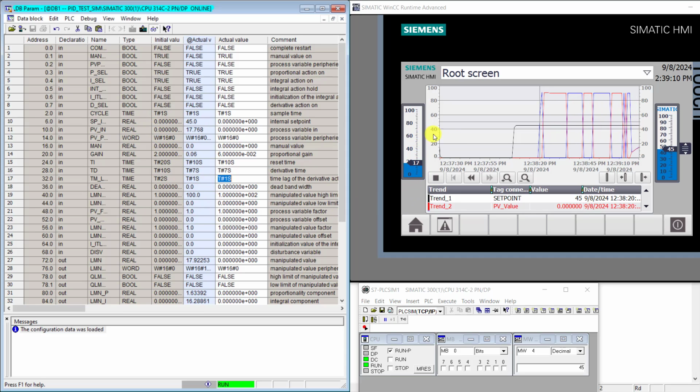And we can see that this time the PID is acting correctly and is trying to force to achieve the set point. And it's going gradually. We can see that it's a bit sluggish. So we need to try and tune it well again. So let's see. You can see it's taking quite some time to reach the set point.